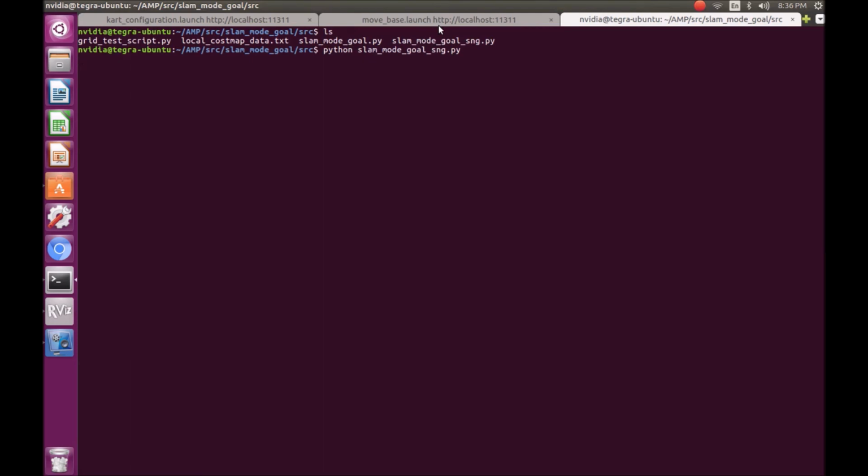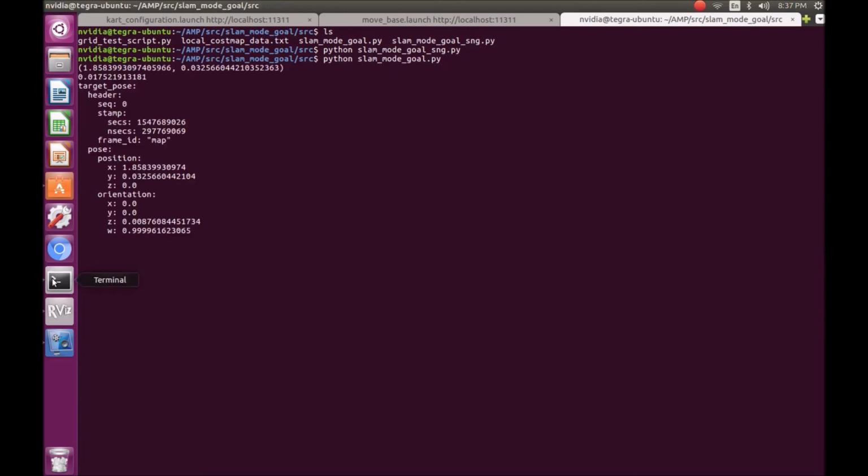So this is what we have solidified and very functional as of right now. What we are currently working on is being able to create Python scripts to do its own path planning, to find, if we go back to RViz here, the best way to move about a track or to move about a room in order to map it.